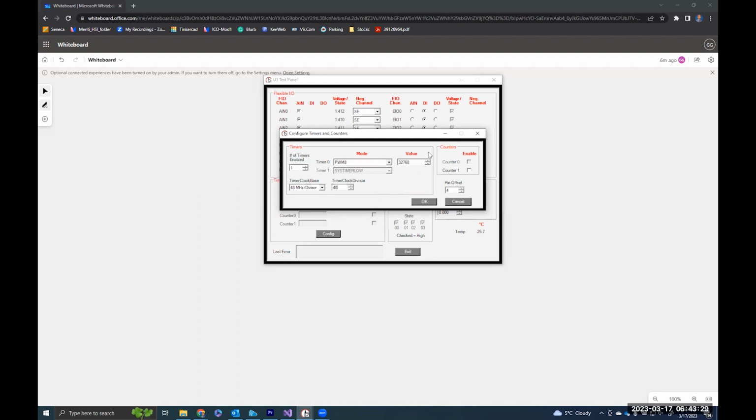And what we see here is the duty cycle. The duty cycle we can adjust according to the lab. According to the lab, we need 50%. So 100% is going to be 65,536, and for our lab purpose, we are setting it at 32,768. All right, so that's what we say.